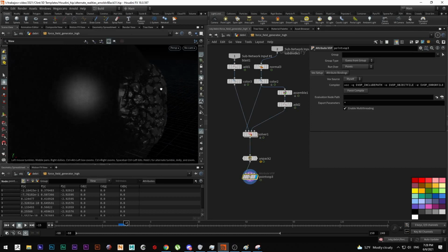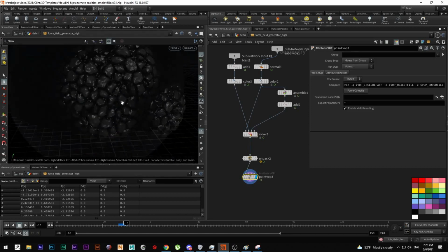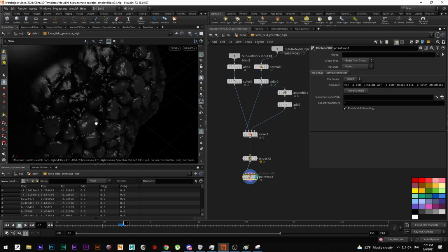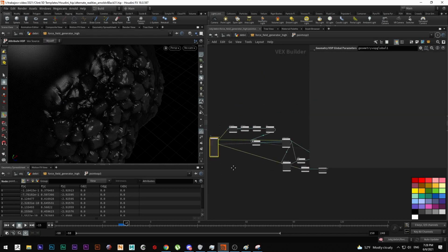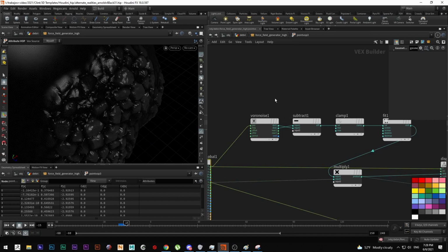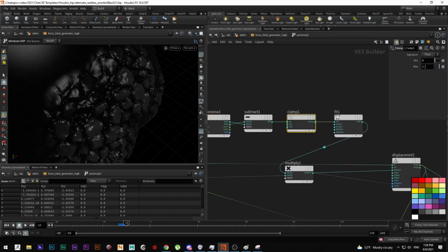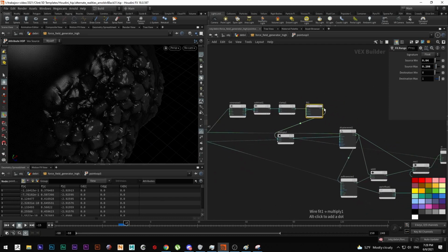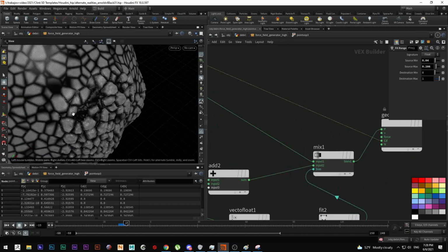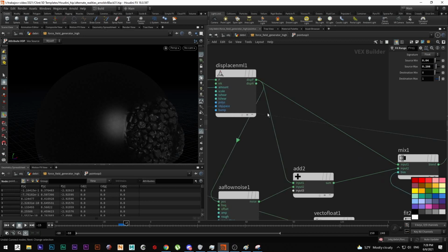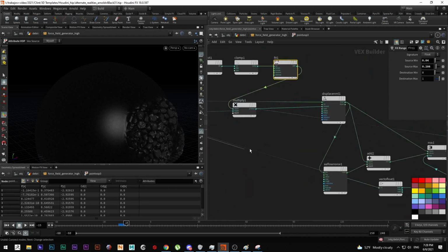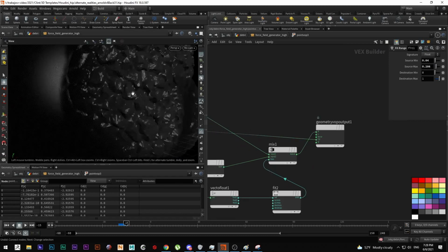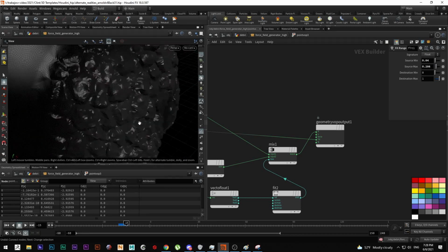generate this kind of motion. Okay, this is kind of broken because I guess it's not the last product, but we can see that we have like a noise being multiplied with this kind of motion. This is a Voronoi noise clamped from 0 to 1, otherwise I would have -1, and I made a function out of it. If I connect this to the color, I have everything here. What I did is masking the color which came from the solver, which is in this case white. It looks like gray, but it's actually white.